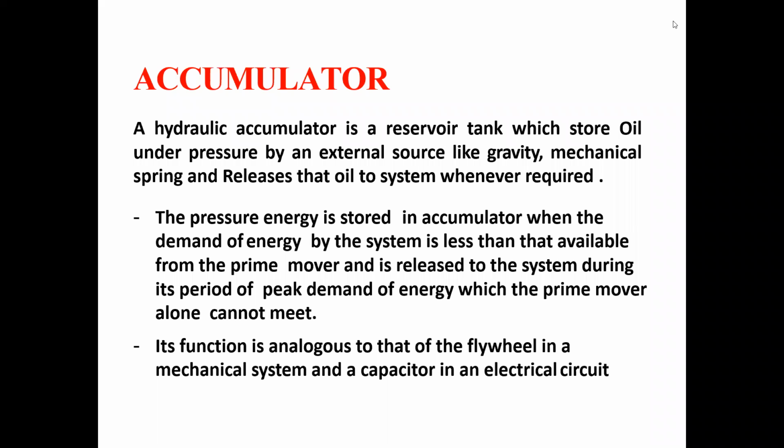A hydraulic accumulator is a reservoir tank which stores oil under pressure by an external source like gravity or a mechanical spring, and releases that oil to the system wherever required. It is a device which stores high pressure oil, which will be supplied when there is a need for more pressure during the peak period.